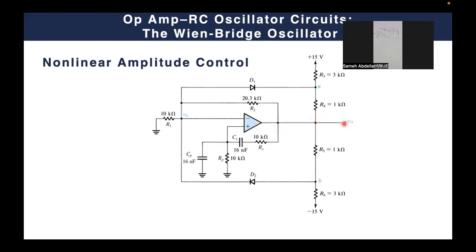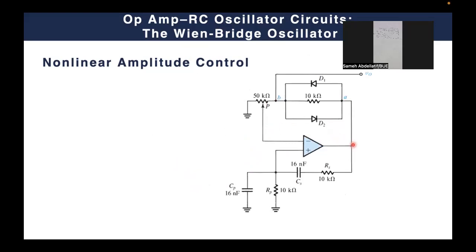So it's the output of the oscillator. And also this is the point carrying the positive feedback to the beta network. If we recognize that this is our beta network, the input of the beta network is this terminal, which is typically the same as the output. Again, as you can see, it's a central node here. However, the input for the beta network, which is conceptually the output of our amplifier, is this node. However, the output of the oscillator itself is this node.